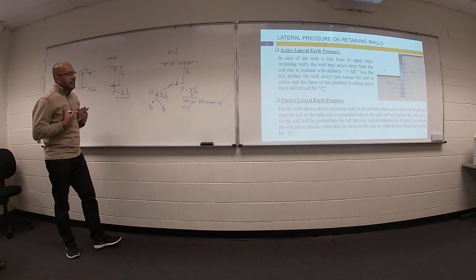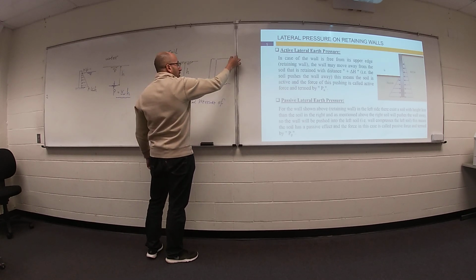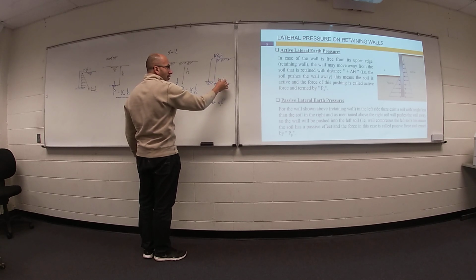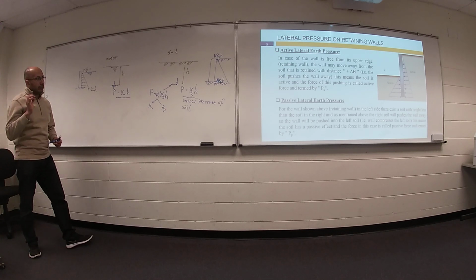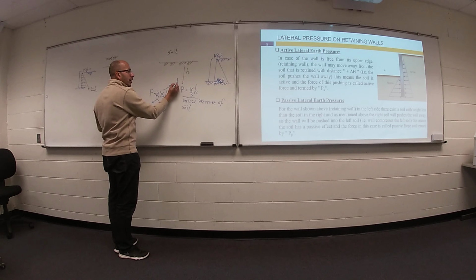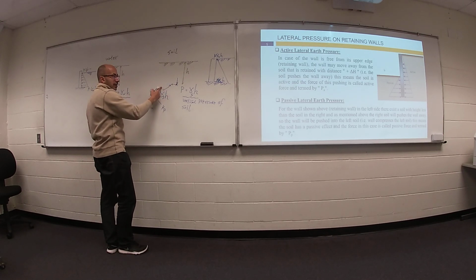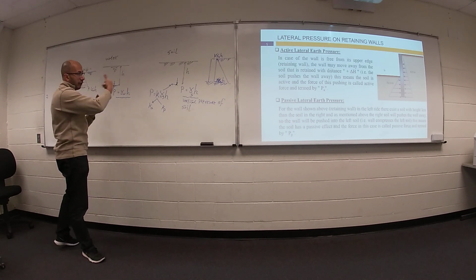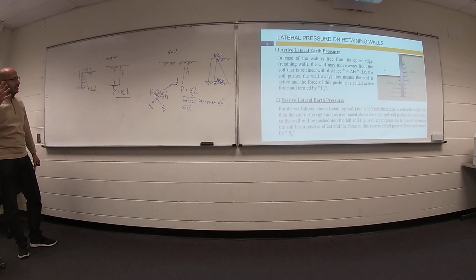You got it? So I suggest, if you would like to determine the lateral pressure of soil, you have soil here. Okay, what is the gamma soil H? Then times K. What is the value here? What is the value here? And then draw your line. So remember, for soil, at any point, we have two different values and two different shapes of pressure: vertical pressure and lateral pressure. Your vertical pressure at any point inside soil looks like pressure for water, gamma H, but this time gamma soil. The lateral effect will be smaller because this K is smaller than 1. So your lateral pressure will be K, maybe K active or K passive, times gamma H.